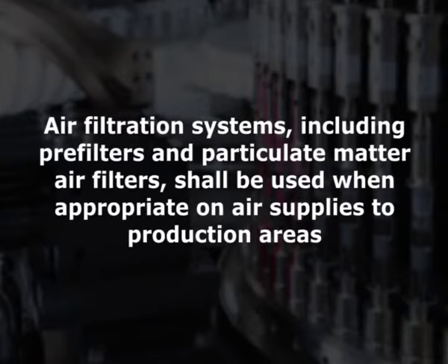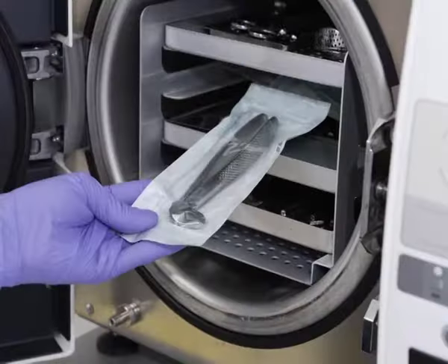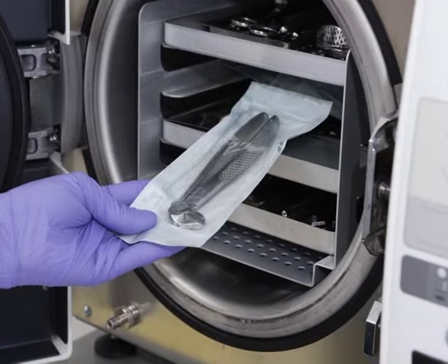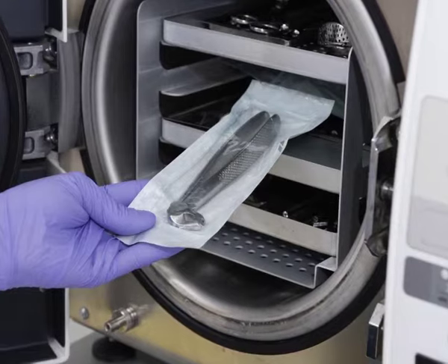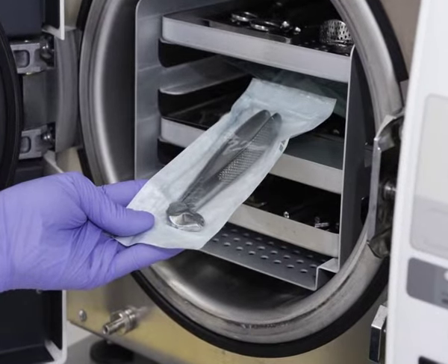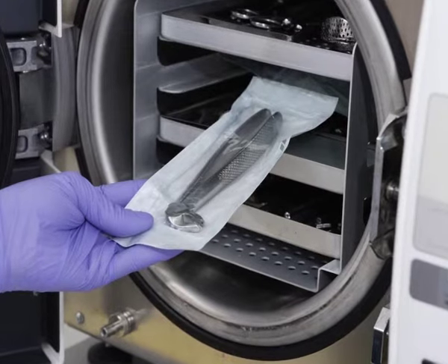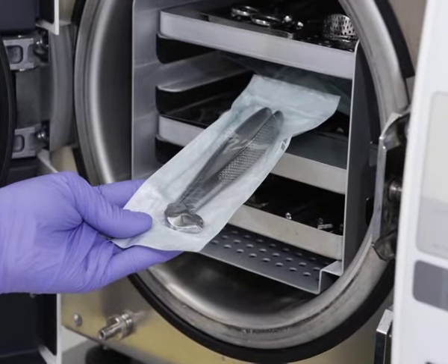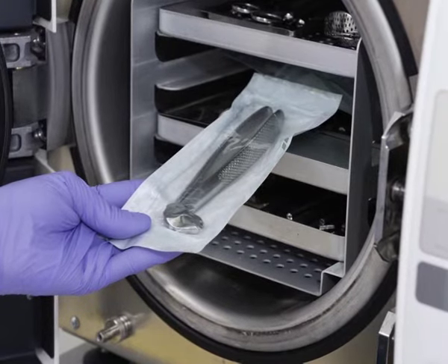Equipment shall be constructed so that the surfaces that contact components, in-process materials or drug products shall not be reactive, additive or absorptive so as to alter the safety, identity, strength, quality or purity of the drug product beyond the official or other established requirements. Equipment shall be cleaned, maintained and sanitized at appropriate intervals to prevent malfunctions or contamination that would alter the safety, identity, strength, quality or purity of the drug product beyond the official or other established requirements.